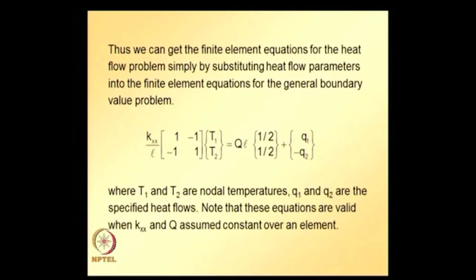So, for one linear finite element, for this problem, these are the element equations. If you have more elements, for each element we need to get equations based on this, and then we can assemble the global equation system, apply the boundary conditions and solve for the nodal unknowns.